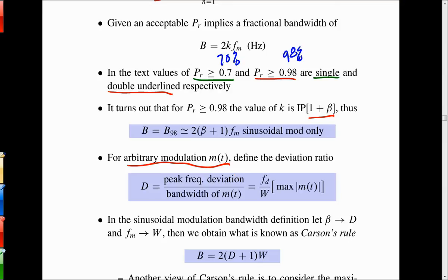So that positive push up is the peak frequency deviation. It shifts above FC by the peak. It shifts below FC by that same peak if it's swinging symmetrically. So that's what peak deviation means. It's a combination of the amplitude of the signal, its max value, and the deviation constant of the modulator, and I'm using the VCO analogy because that's a simple view of an FM modulator.